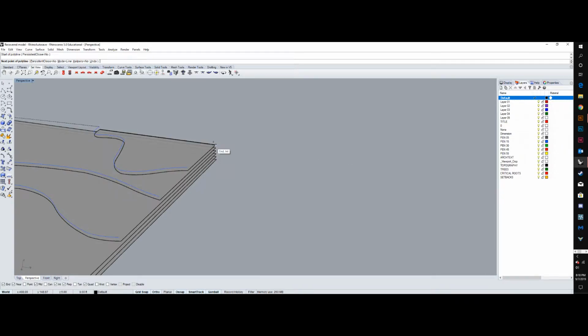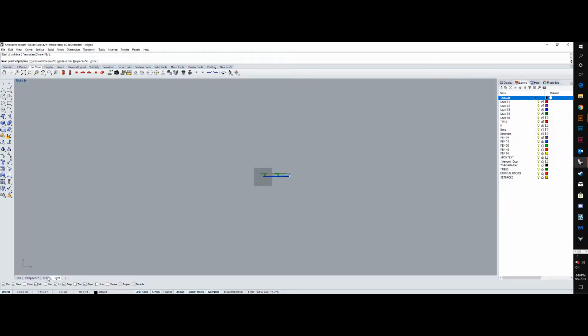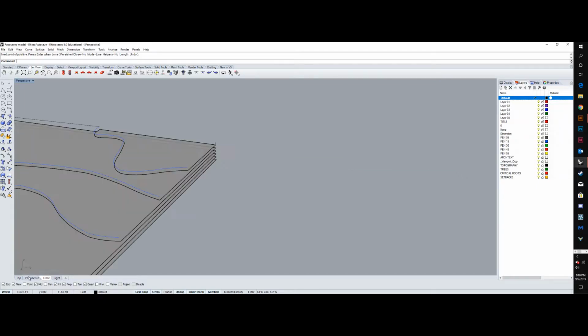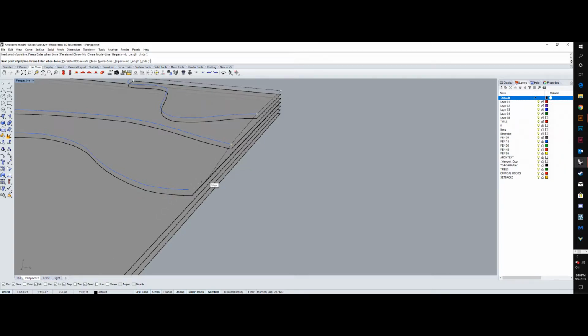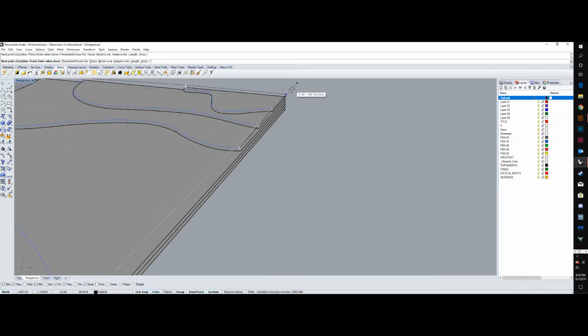So I'm going to make a 1 foot vertical line here. And the way I'm going to make it vertical is go to the right view or any view like the front view. I'll do front view. Any view that deals in verticals. I'm going to go vertical here, type in 1 foot, enter, and then enter again. Now I have a little placeholder line to tell me where to continue. And I'm going to continue my little perimeter, my little dance around the model.